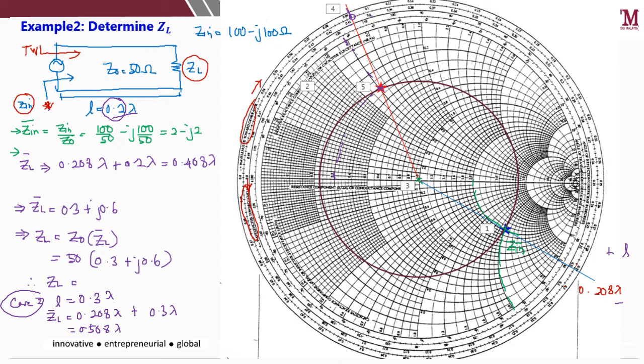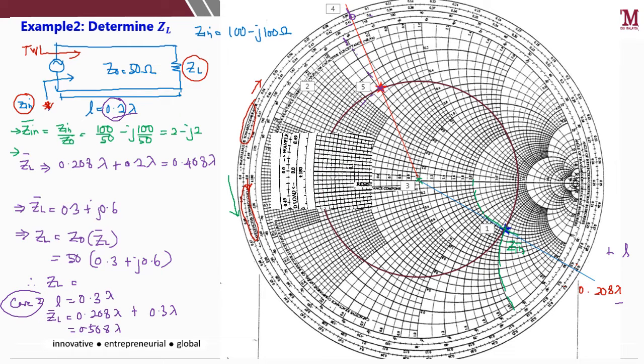Okay, if you look at this Smith chart, this is to determine L towards the load, facing anti-clockwise. If you refer to the scale, you'll see that the maximum is only 0.49, meaning here is 0.5 lambda. The maximum length is 0.5 lambda, but now how to get 0.508?